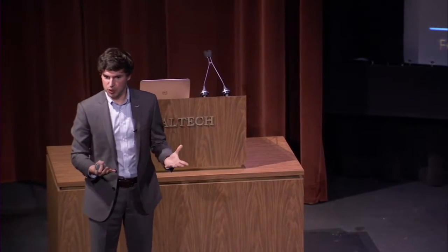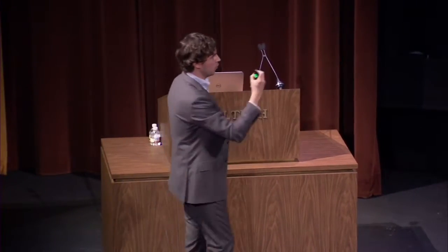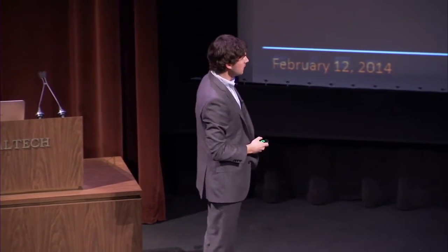What you need for these mirrors is a material which, of course, is strong and stiff. You don't want this to deform easily. But at the same time, you need something that cannot vibrate if it's being hit, for example, by space debris. Imagine you're standing in front of your bathroom mirror in the morning, and all of a sudden the mirror starts to either deform or to vibrate. You're not getting a clear image. You're at most getting sick. The same thing is what we see here. We need materials which damp vibrations, which absorb the energy of vibrations.